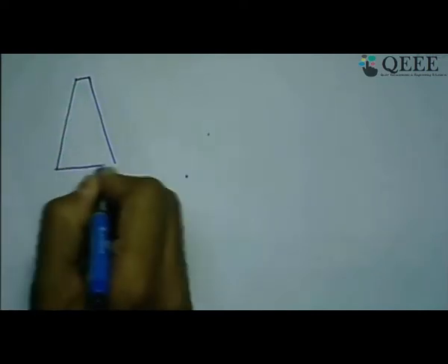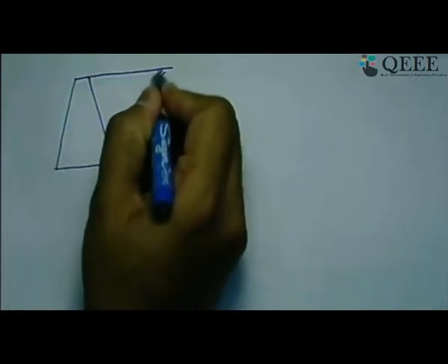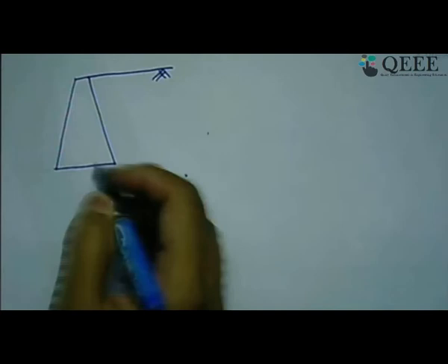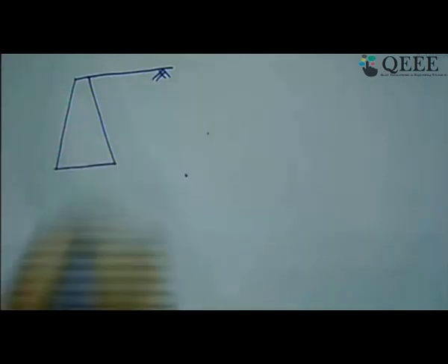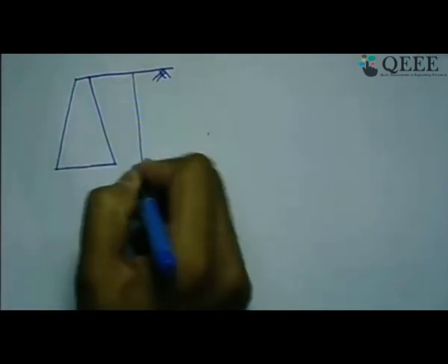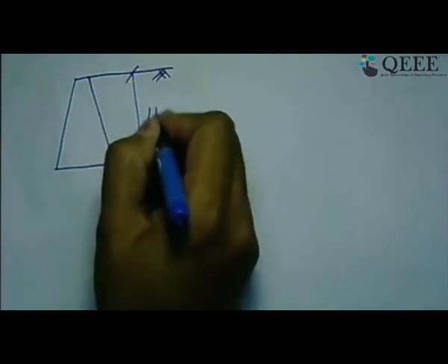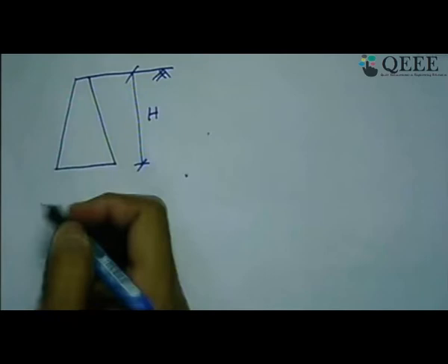So typically a gravity retaining wall will have some shape something like this. Now, as some of you were asking, what should be the dimensions of these things? The height of the retaining wall, you get from your requirement, that is what level difference you want to maintain.